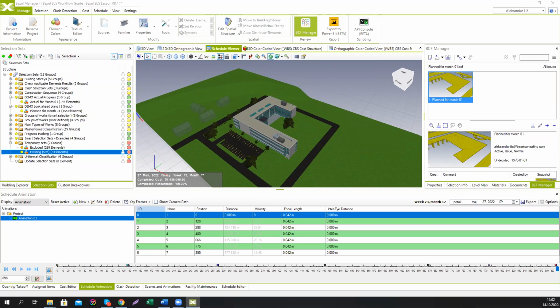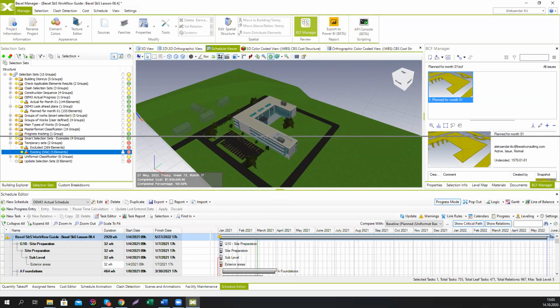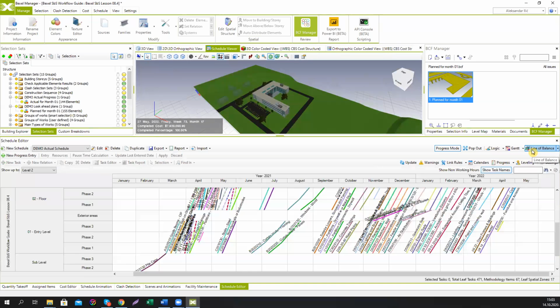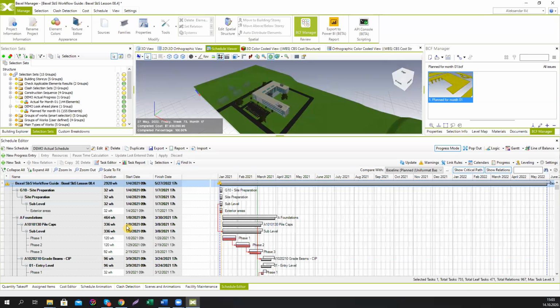So let's see, in line of balance, is it based strictly on resources? When comparing two schedules, having one schedule in construction, is it possible to improve line of balance with the progress of a current construction? No, it's not based strictly on resources. So line of balance in this case is only different view of the schedule. So it's one integrated schedule. It's the same schedule from Gantt chart, line of balance chart, or logic chart. So all the modifications that you make within one of these views is reflected in another one.